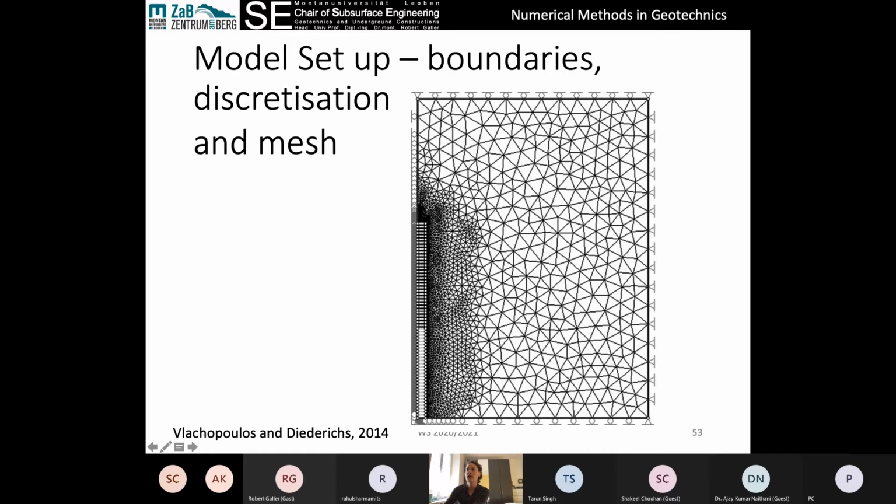This material with the triangle here is not allowed to move in any direction. This is a fixed boundary. So this is common boundary condition notation, these little triangles and these little rollers that demonstrate no movement and movement in the X direction and movement in the Y direction.